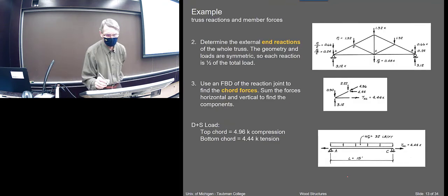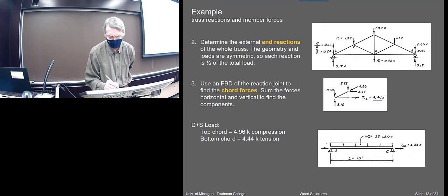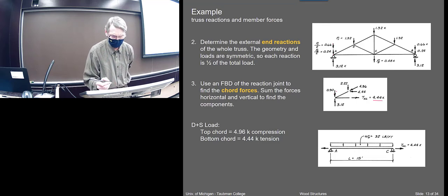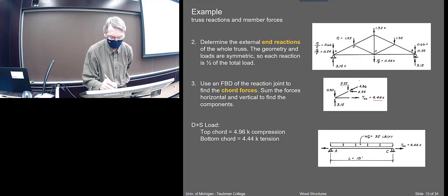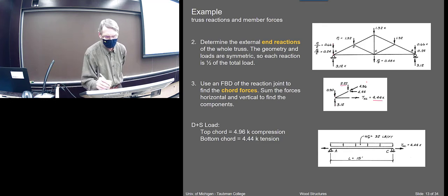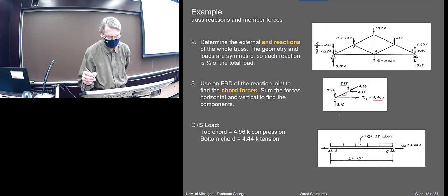We can go ahead and, based on that, do a little free body diagram and get the axial forces. So the axial, well, let's see, I added these, and that's going to be that load. And then if I subtract that from that, I'll end up with that, right? That's summing the vertical forces. And then, what was the height?